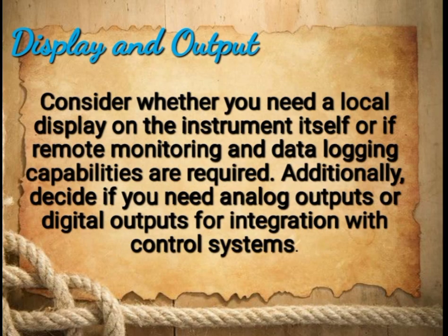The seventh one is display and output. Consider whether you need a local display in the instrument itself or if remote monitoring and data logging capabilities are required. Additionally, decide if you need analog outputs or digital outputs for integration with control systems.